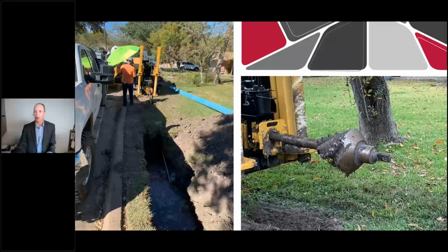So that's the photo there on the left with the drill rig and the drill rod you can see going into the entry pit. And then the photo on the right is a photograph of the reamer, where they back reamed for that 8-inch water line. And so you can see what that looks like as it spins and makes the hole bigger. And then there's the hook on the end of it, or the opening notch where they can connect the pipe that they're pulling into place.